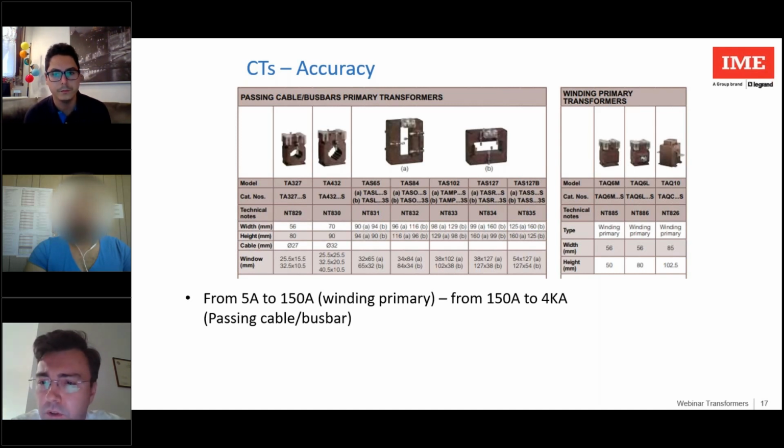Boris, don't you take a risk if you select a lower current ratio for the CT compared to the breaker values? If you saturate the CT, or if you change loads after a time, the change of CT might not have been documented, but the breaker is.